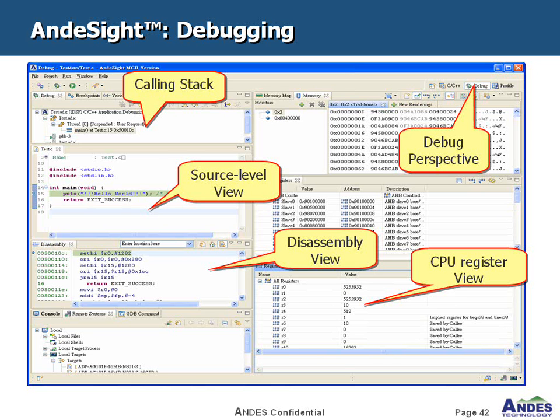The other, you can monitor memory by this view. The view is very useful. It can support CPU mode and bus mode. It means you can monitor cache in CPU mode and monitor bus memory in bus mode.